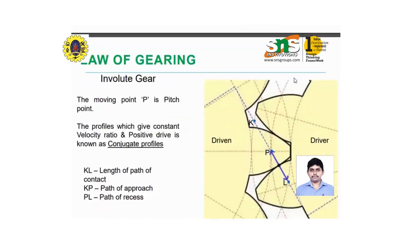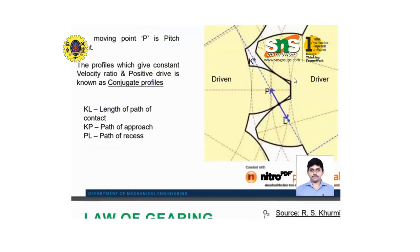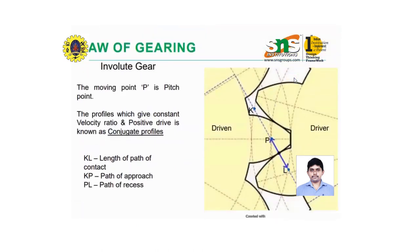Okay, so in the upcoming class we just saw about the conjugate teeth. So here I am going to touch on what is meant by law of gearing and what is meant by conjugate teeth. The moving point P, if you are going to trace the moving point P when meshing takes place, it can create one direction which is angular to the tooth point of contact.